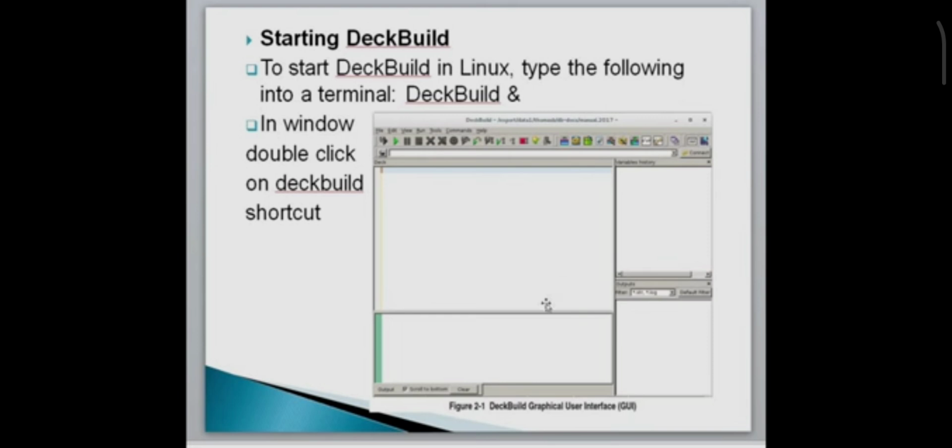The upper portion of the window is the Deck Editor window, where you can either type in the syntax directly or display syntax from a loaded deck. The lower portion is the RTO, runtime output, and the lower side portion shows the saved log and structure files. This will display information generated from the simulation run. The very top has a range of drop down menus and a toolbar, which contain all the shortcuts.